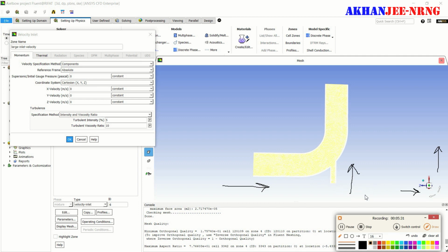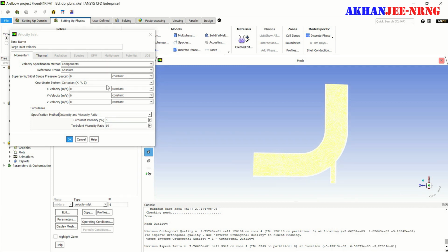Comparing this direction, we notice that the direction of velocity of the small inlet is equal to the plus x direction in the triad. Now we'll input our values. The value of the large inlet water velocity is 0.4 meter per second, in the minus z direction. So input the value for water in the large inlet velocity: minus 0.4 meter per second.